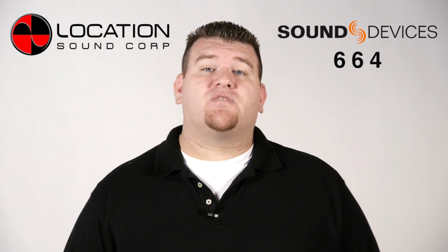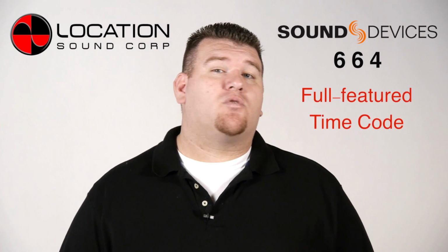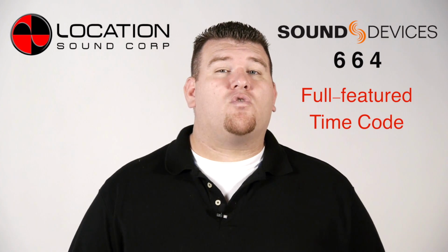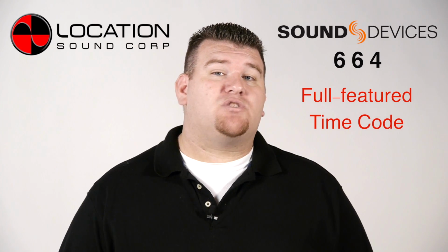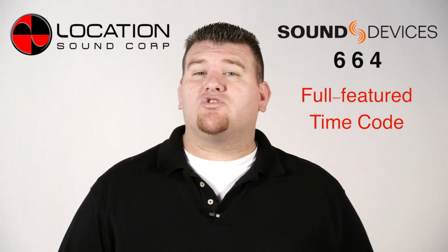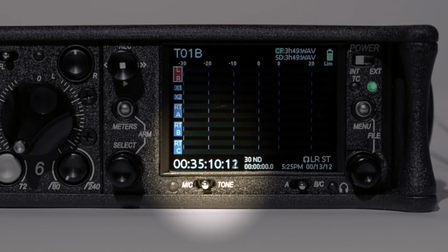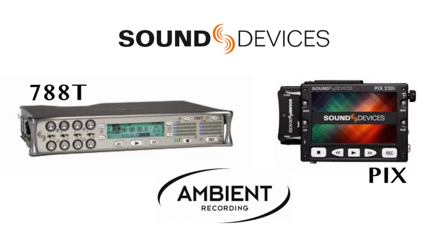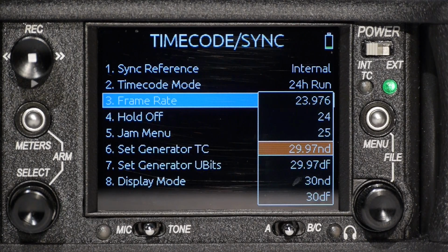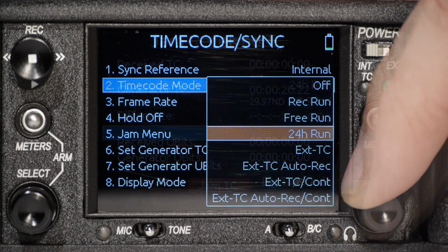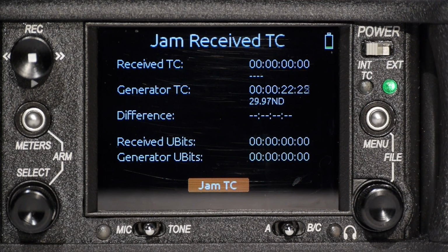One of the unique features of the 664 is its full-featured timecode capabilities. The 664 holds accurate timecode for up to 2 hours between battery changes using its internal rechargeable lithium timecode battery. It comes with a high-precision ambient timecode generator, the same used in Sound Devices 7 Series and PIX recorders, including all common timecode frame rates, timecode modes, and a jam menu featuring a unique timecode compare tool to measure offset from internal and external timecode sources.